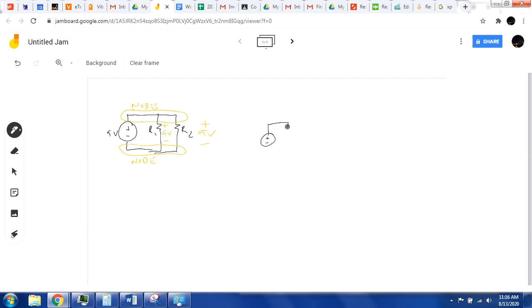Why that's important is sometimes you'll see some sketch on a napkin, which is not much different than what I'm sketching anyway. I mean, this is not great art. But, oh yeah, we got all these resistors that kind of look like this. And believe it or not, those are all still in parallel. Even though it's like, well, what is this mess? Well, if we look at our nodes, we can say here's one node, and here's the other.